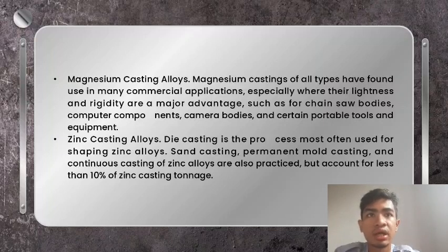4. Hydrogen is the only gas with significant solubility in aluminum and its alloys, and hydrogen solubility in aluminum can be readily controlled by processing methods. 5. Many aluminum alloys are relatively free from hot shortness, cracking, and tearing tendencies. 6. Chemical stability. And the last one, good as-cast surface finish with a strong surface that has few or no blemishes.